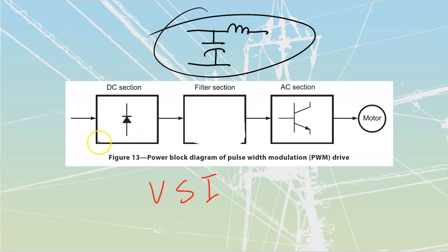They do also have voltage that we take in, and we maintain a constant amount of voltage. We don't need to control the DC section. We just rectify. We take everything in, stuff it back onto that cap. Once we stuff it onto that cap, then we can take it out to our AC section.